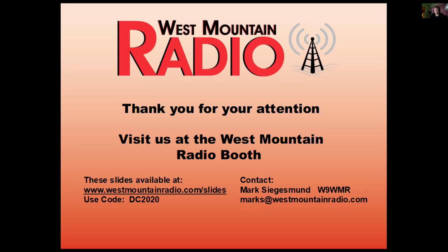Can Epic work with lithium batteries in a buffering configuration? That means charging the battery like 99% of the time. Yeah, many customers do just that. You do need to set the jumper inside the Epic to tell it that it's lithium. That way it knows not to trickle charge. When the battery gets down to a certain voltage, you know, 12 point something volts, it'll start a charge cycle. It'll charge it all the way up, but it won't continuously charge it to damage the battery.